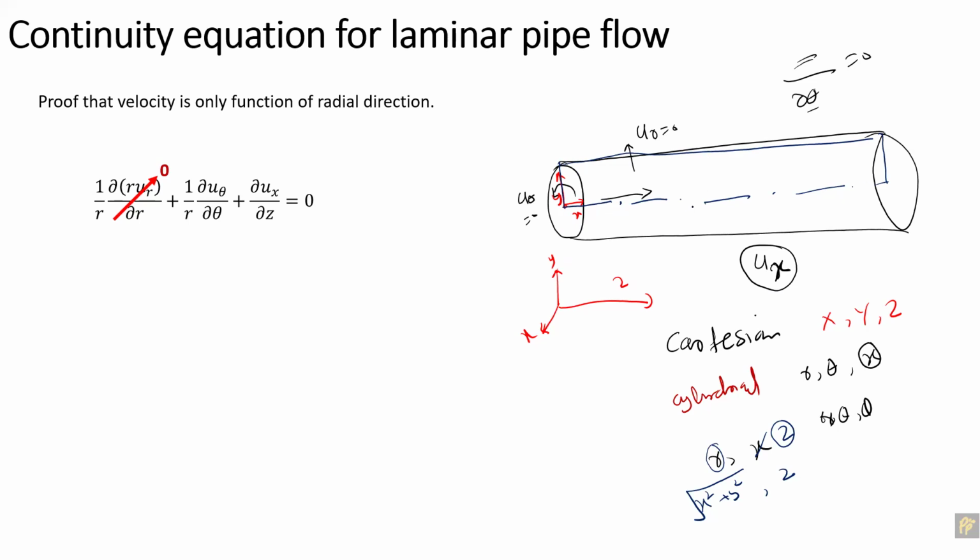Okay. So this boundary will be defined as the axis, and this boundary will be the inlet, like normally in the 3D case also. This is the outlet, and this will be the wall, a no slip wall. The only extra boundary condition is that Fluent has the option to solve the case as 2-dimensional axisymmetric. So this is going to be the axis. Actually, the solution from the 2-dimensional axisymmetric problem and the 3-dimensional simulation should give you the same results.